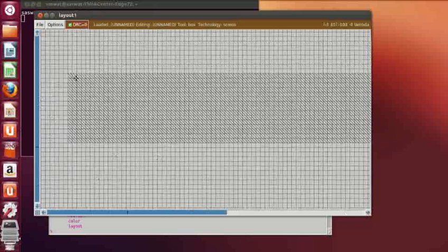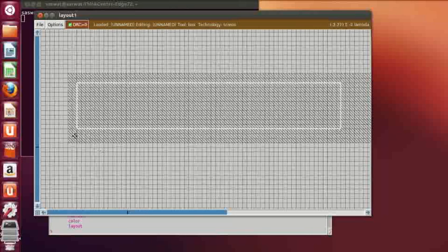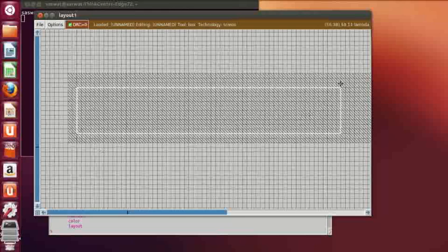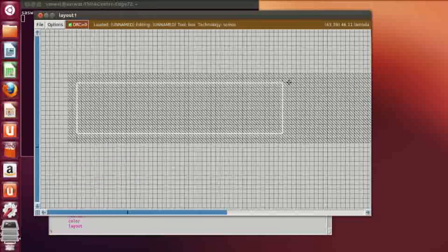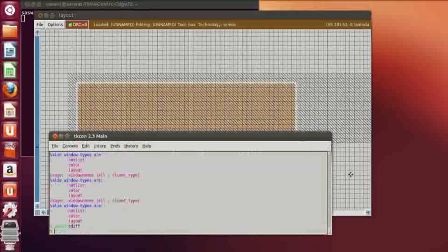the two PMOS, that is the first and the second PMOS, they have a common drain. So we can draw like this for two at a time, or we can even reduce this area up to this much, and then type paint pdiff, that is the p diffusion layer.